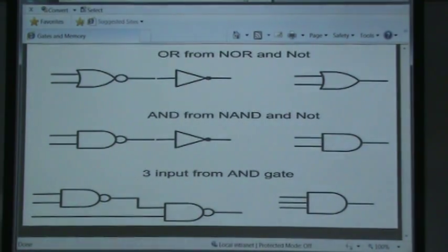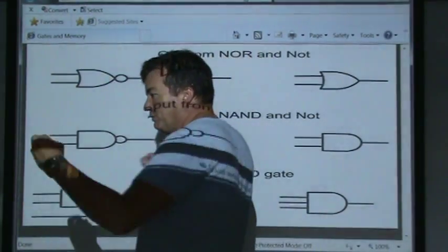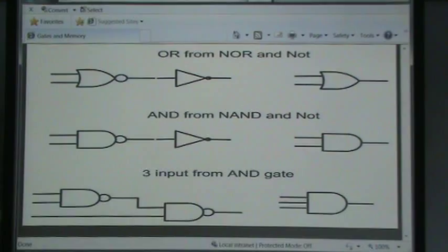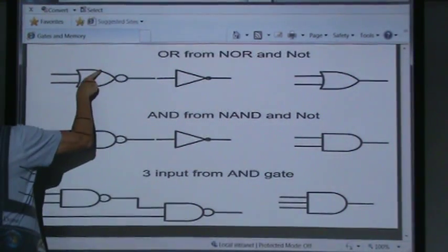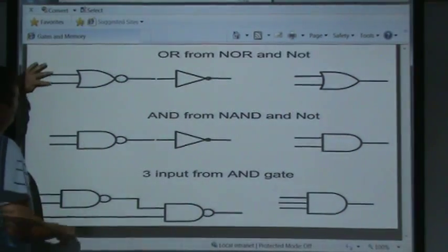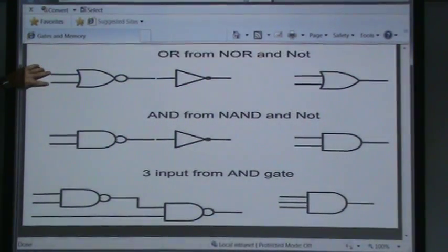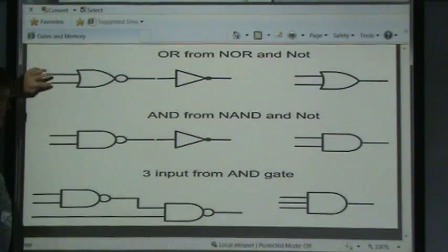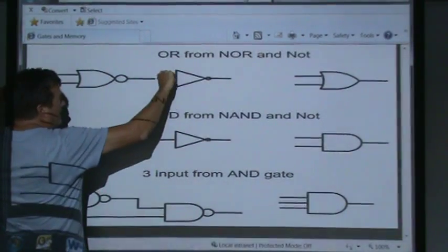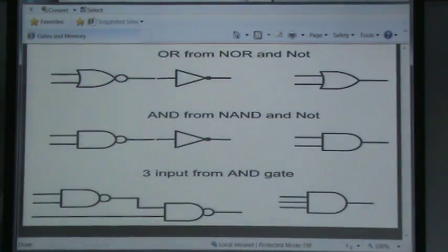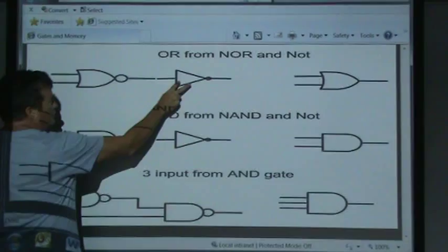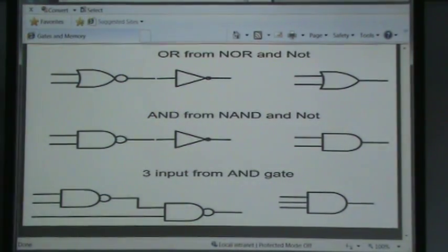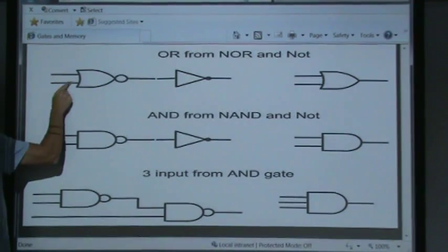So what we can now do is start taking the NOT AND and the NOT OR and the simple NOT gate and just plug them together and start making new gates. So for example, if we take a NOT OR gate, so that we're asking, are these two bits both 0? And if so, a 1 will come out of here. And then flip that. Then these 2 gates put together would be equivalent to an OR gate. So what we're really saying at this point is either one of them.